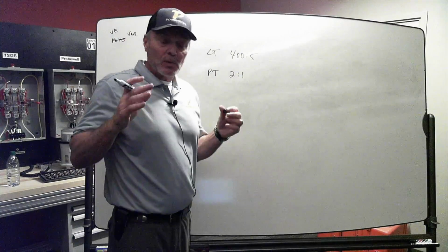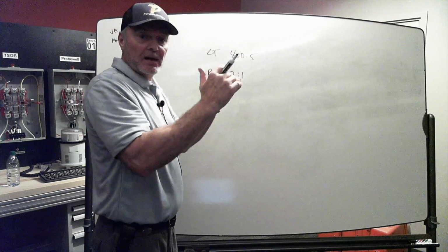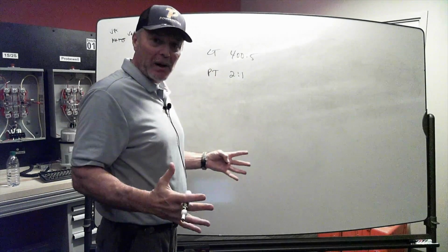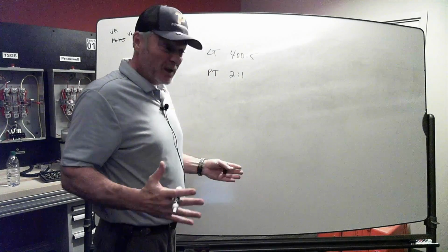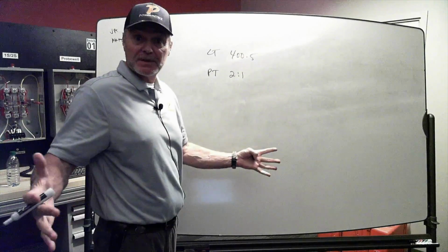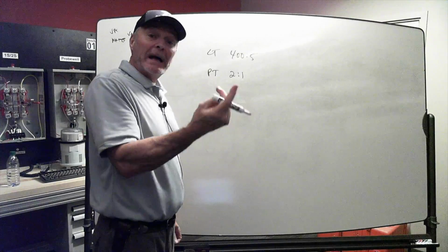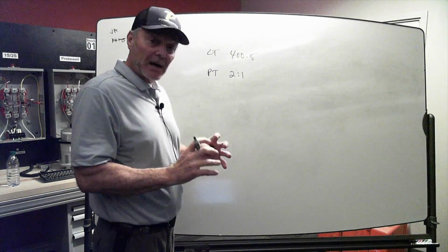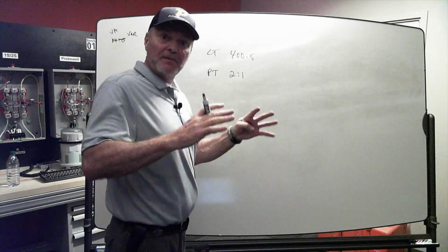If you think about it, the reason why we're doing all this step down of these transformers is to think about the type of equipment you would have to have at the bottom of that pole to handle that much power. You'd have to have blades that thick on all this. The test switches would be monstrous. There's another reason why it's done the way it is: if we step all this down and have less power available at the bottom of the pole, we can downsize all of the equipment down there.